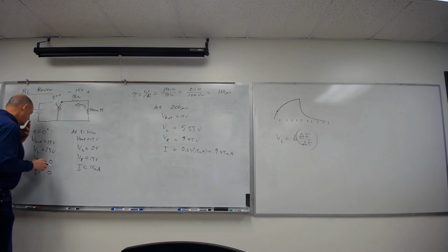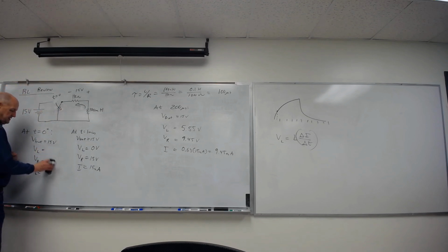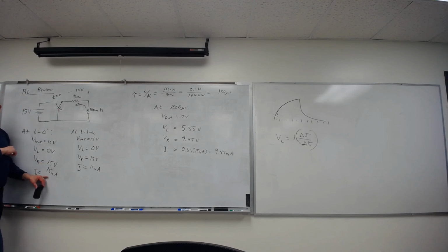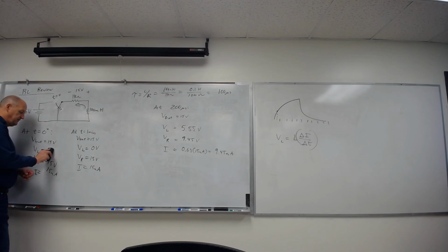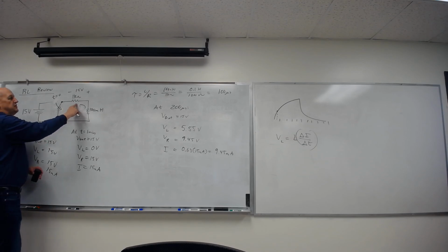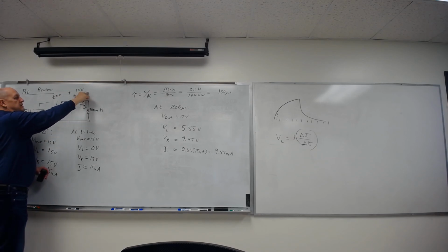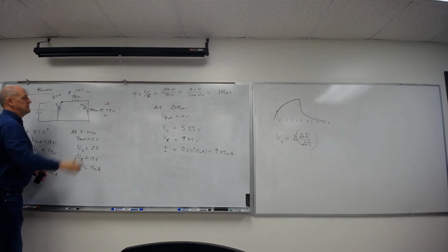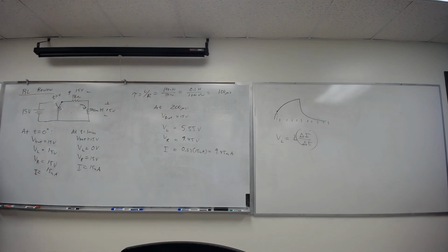There we go. Okay, in that case, it's been sitting there a while, so we had a constant 15 milliamps, constant 15 volts across here, and 0 volts before the switch closed. Now the switch closes, no instant change in current, which means no change in the resistor voltage. But this voltage has to immediately jump up to 15 volts because that's my circuit. In this case, the current's still going the same way. So the resistor is just holding the voltage and the current going. It's just going to take a while to ramp down.